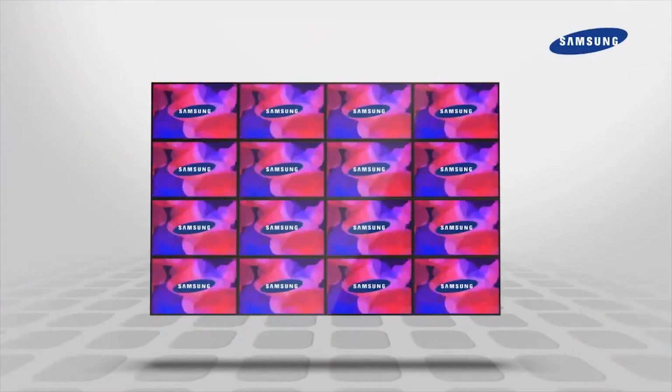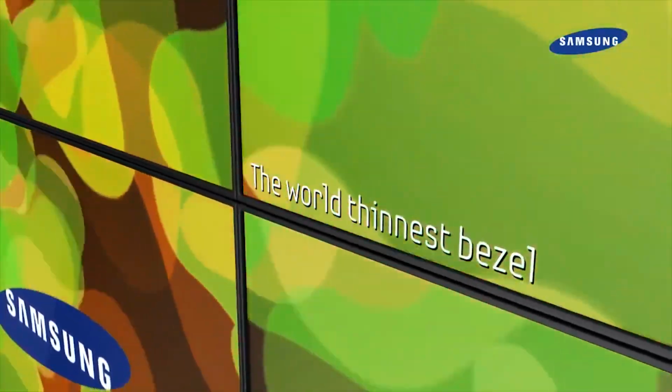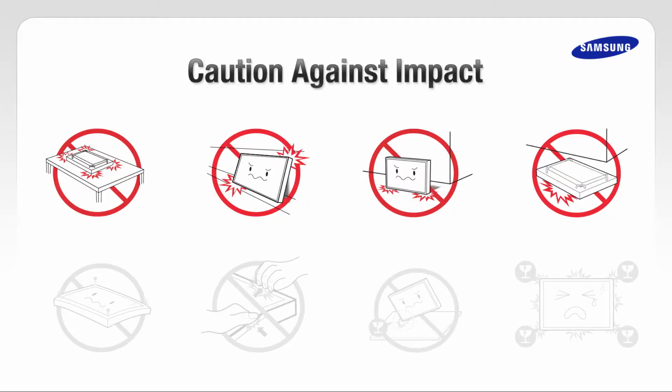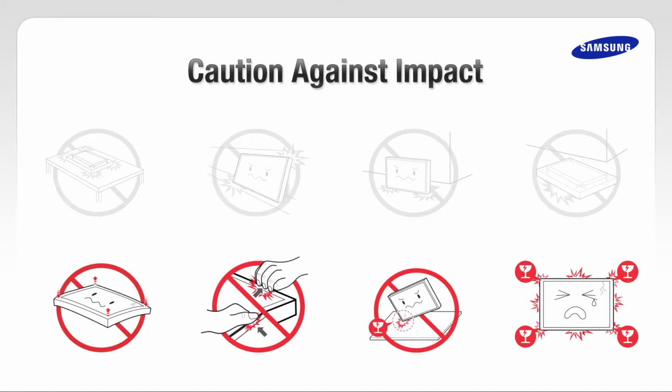The LFD for a video wall has a slim bezel and is very weak. After opening the box, carry the LFD carefully. Caution against impact. Set the LFD box on the ground and stand it up properly. After opening the box, be careful not to lean on the LFD to avoid damage. Do not forcefully push on the edge of the LFD.